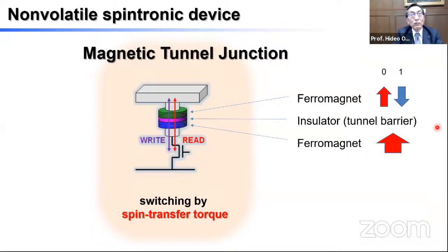People were looking for magnetization perpendicular to the plane, so perpendicular to the device's lateral dimension. But people were having a very hard time finding a good material system to do this without sacrificing other features that we want a magnetic tunnel junction to have.